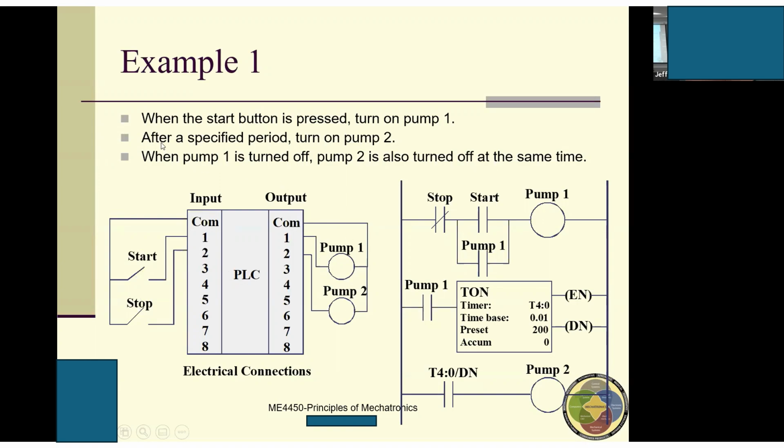And our customer gives us the following requirement. What is the requirement? When the start button is pressed, the customer wants to turn on pump 1. After a specified period, which should be adjustable, pump 2 will be turned on.